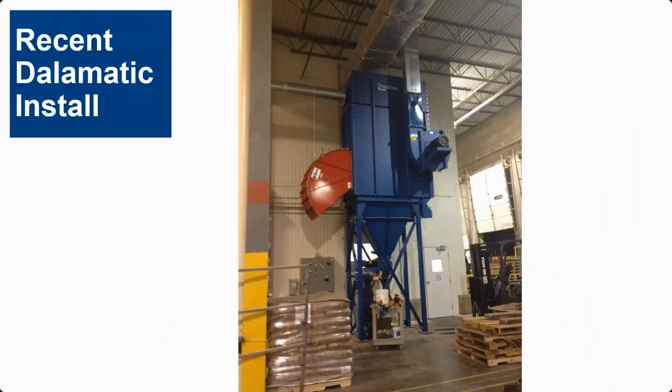This is an example of a Dalamatic that we did recently. Again, you can see that you've got a Fike flameless vent there, so we must have combustible dust. The fan is exhausting either outside or to a floor above. I'm not sure what it was on this application. But you also have an NFPA airlock here, and the controls conveniently located right next to the collector.